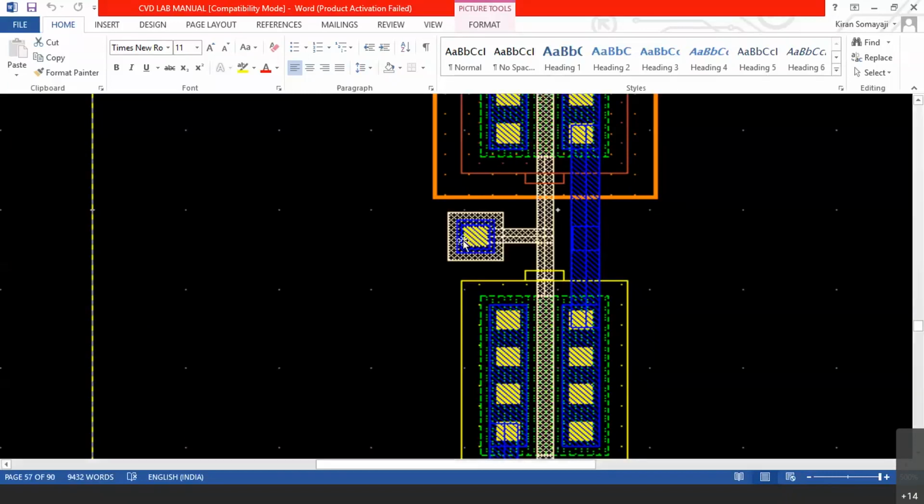That is why there is an additional area beyond the contact area. Metal area. Again, additional area for a polysilicon also. This way we place a wire. Wire will always contain now 3 layers. That M1 to poly 1 wire will contain 3 layers now. That is polysilicon below, in between it is tungsten and above which it is metal.